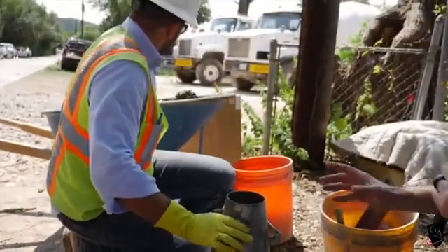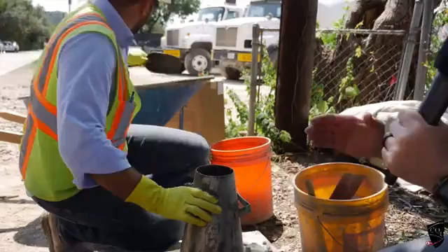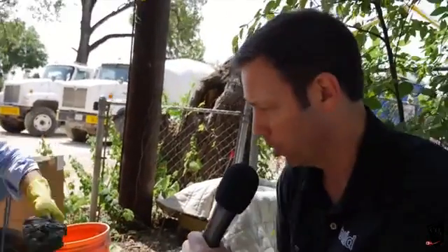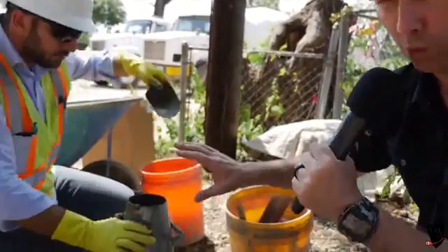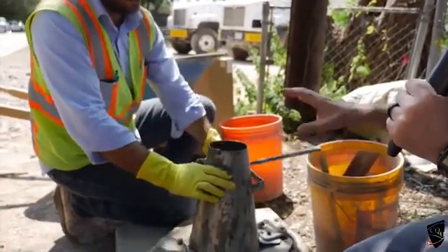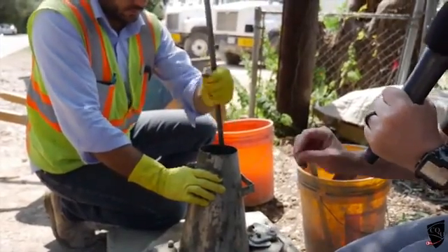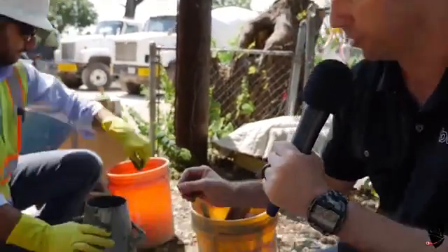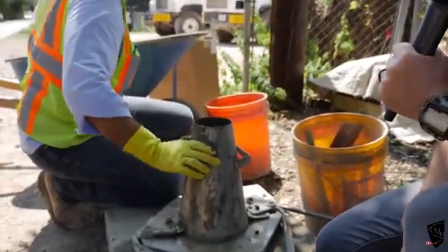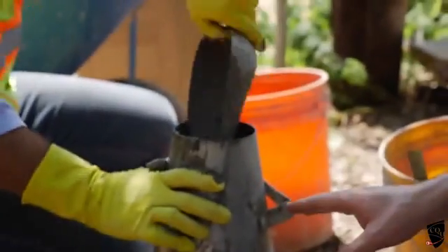He's doing some other tests for us, but this is a test that you could do on your own house. No matter what you're doing, this is a good test. What we're generally trying to figure out here is how much water is in the concrete. First, you want to check what the engineer has specified for the mix, and he's usually going to put a slump value on that. Then the ticket from the concrete company is also going to say what the slump is. In this case, we've got a 5 slump mix coming from the concrete company, and we're going to be able to test that with this cone.